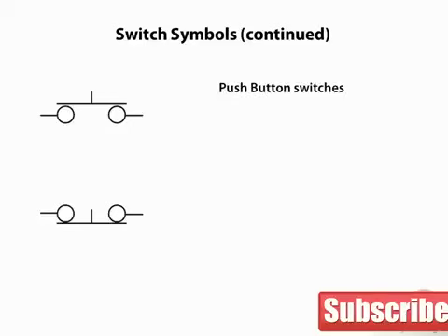They control their contact closures by push action rather than toggle action. They can have the contacts momentary, that is, the switch needs to be actuated to hold or release the contacts, and a spring in the switch returns the switch to either a normally open or normally closed position when not actuated.